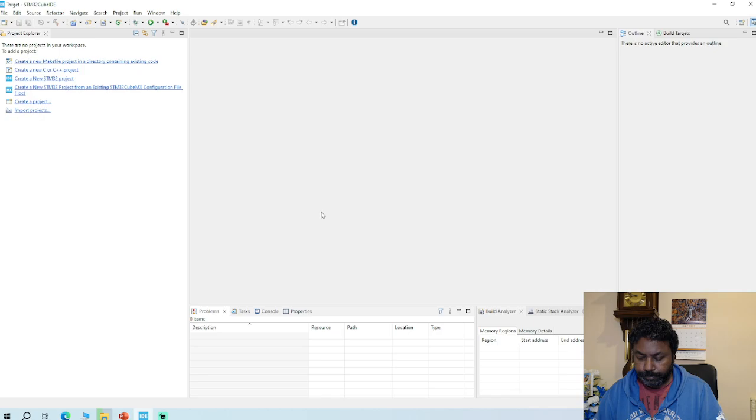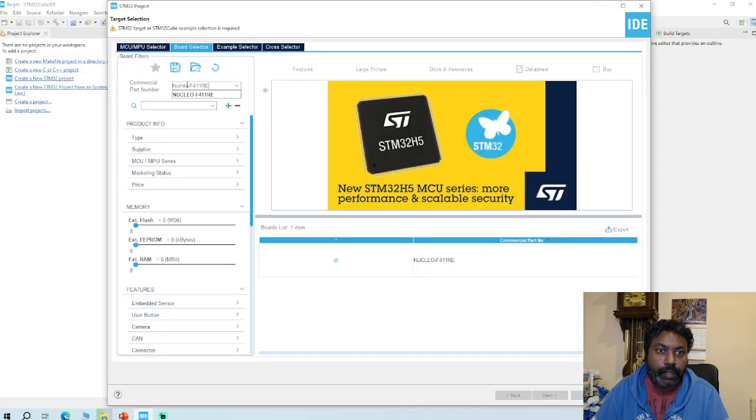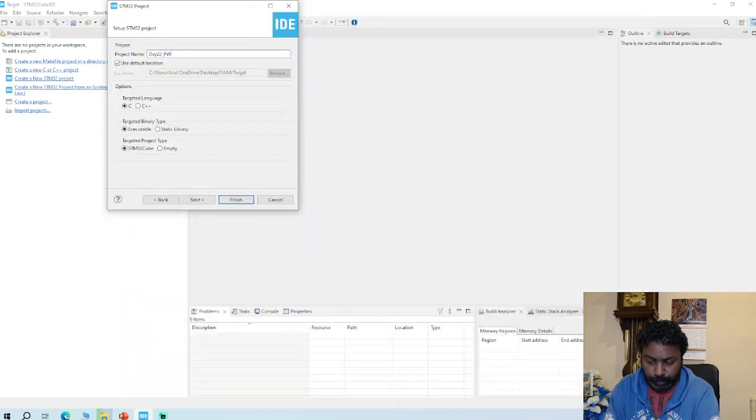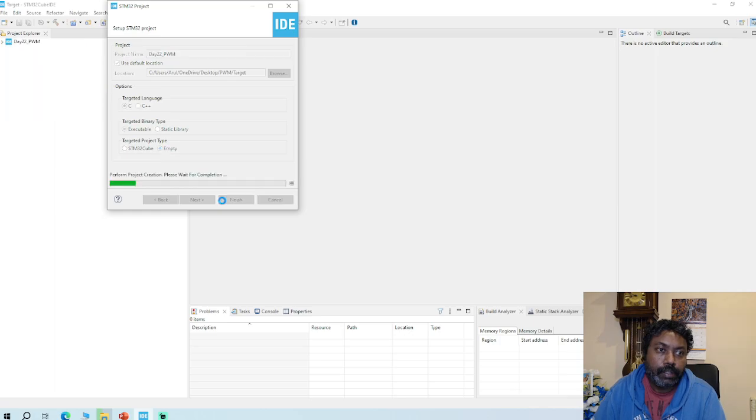Okay, you know where to go. So board selector, and then type in Nucleo board, Nucleo F411RE, and then select this board, click next, and give a project name. We are on Day22, so I'll represent that. Day22 PWM, and we're going to start from scratch. So select the target project type as empty and then finish. This will create the project tree.